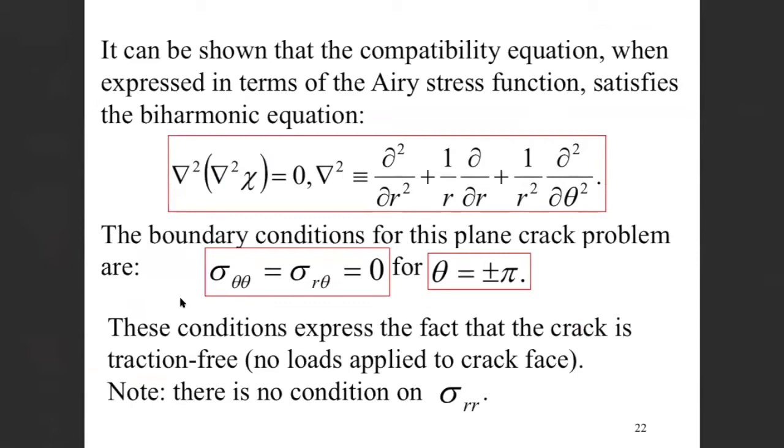So where is the origin of the crack? Center or the edge? Origin of the system. It's an infinite plane, so the origin is 0. So the tip of the crack is 0, and it starts at negative infinity, and the crack tip is at 0. So if we have this crack here, this needs to be stress-free. This is a free surface, and obviously shears along this plane need to be 0.